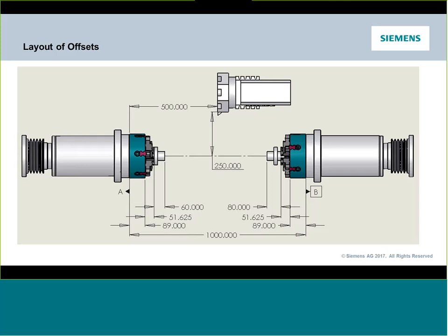Now, in addition, we're going to need to know some information about the work holding. And we're going to see here in a sec how I start to plug that into the control. But it's important that you know the chuck body size and the jaw projection size. Once you have those, you're also going to need to know where you would want to have the part sitting in those two clamping orientations. So how far out do I want to stick it for this job? And then when I go grab it, how far out do I want it to be sticking when it's all said and done?